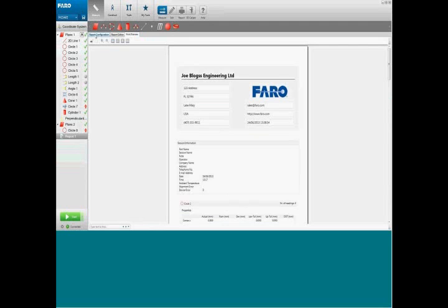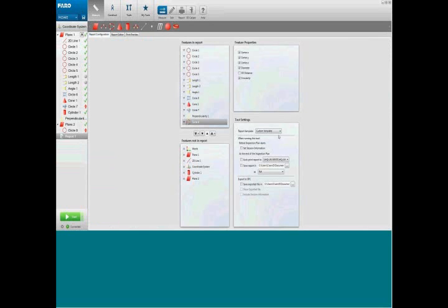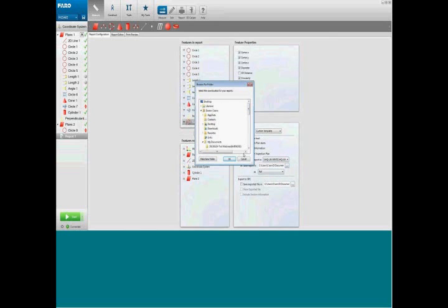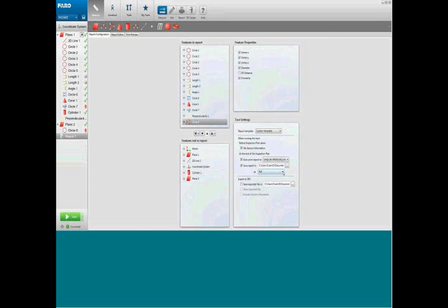To run a report, just to continue down the side, we have the set session information here, which allows us to prompt the user for the part number, the operator, etc. before the tool is run. At the end of the inspection plan, we can choose to automatically print to a printer, and we can choose this from the options. We can automatically choose to save the report in a set location. And we have two types, either PDF or XPS.